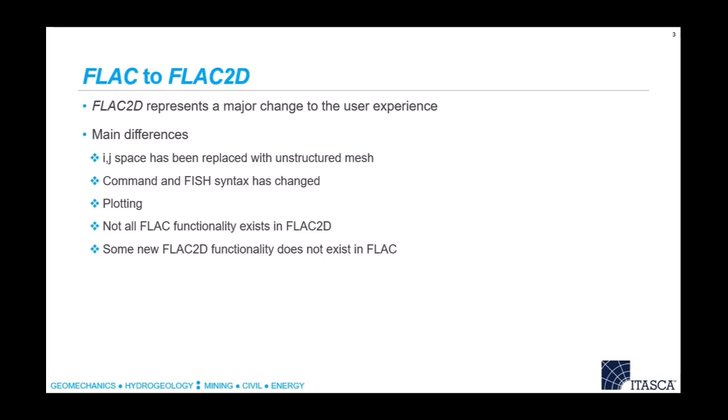Anyway, what you have is a situation where the old FLAC and the new FLAC2D are quite different in terms of the command and fish syntax. So part of this exercise was to bring these things together and make life easier for people who are trying to use both 2D and 3D. And certainly our own consultants find this super useful because they're often using both things. Out there in the real world, there's maybe less people that use both. But if you do use both, it's certainly super awesome now because they're basically exactly the same. And similarly, the plotting is now the same in FLAC2D and FLAC3D.